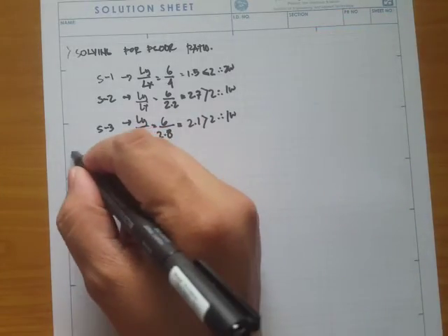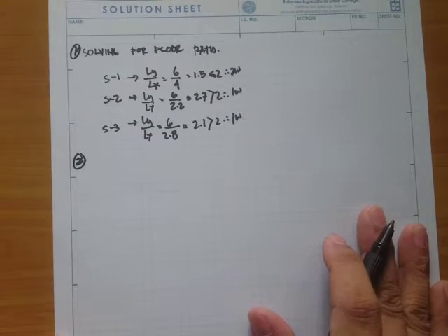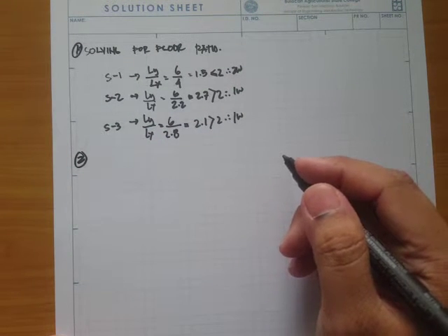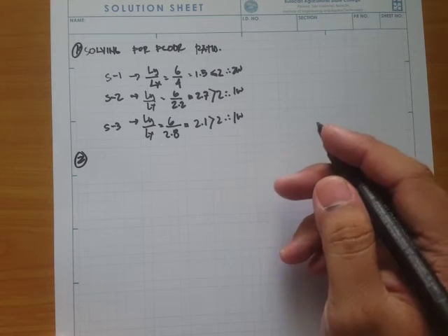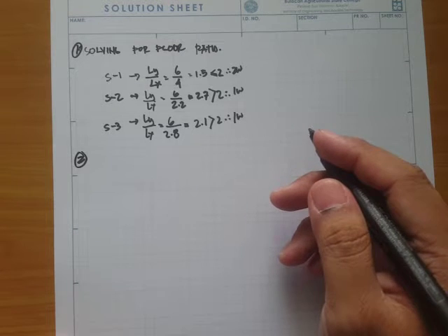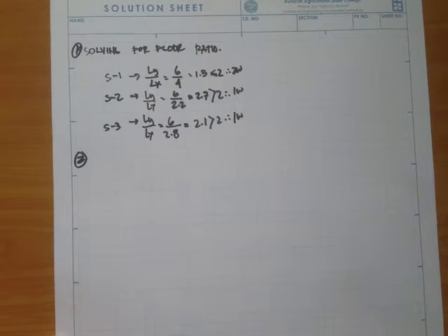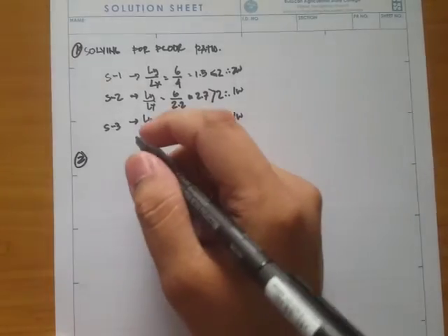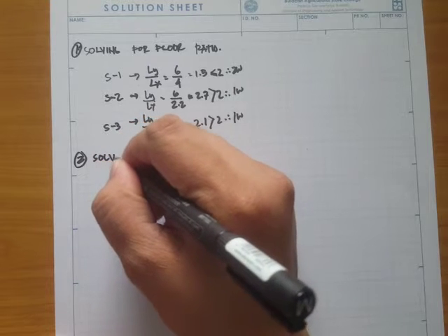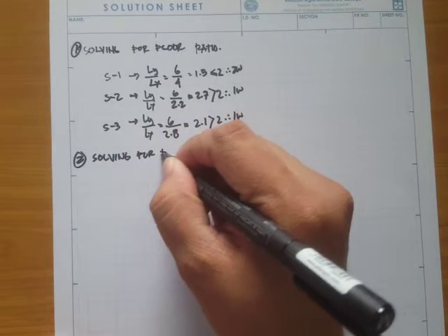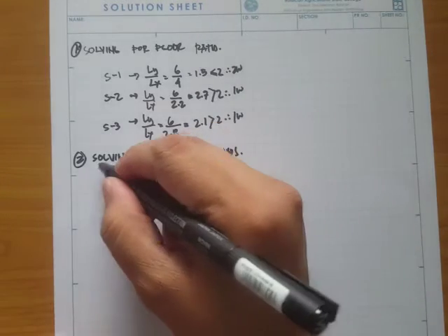Okay, so let's just write step number 1. Then the next step, we can solve for the factored loads. Since most of the beams will have their loads coming from the slab, we can solve for the factored loads on the floor.